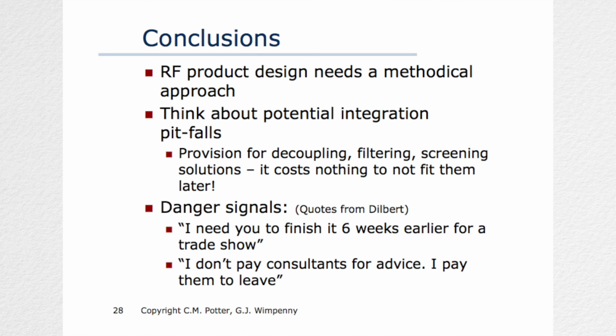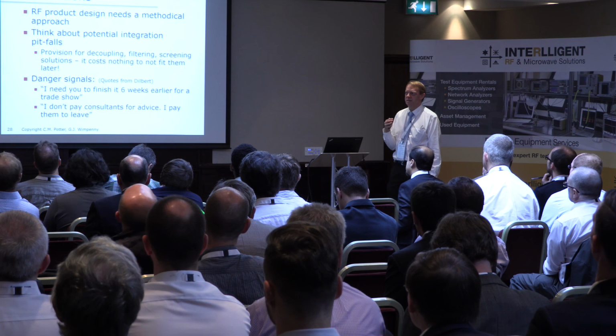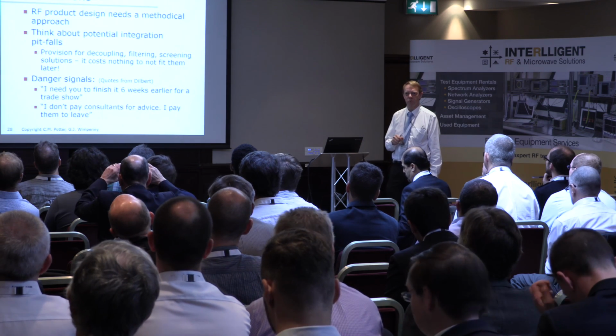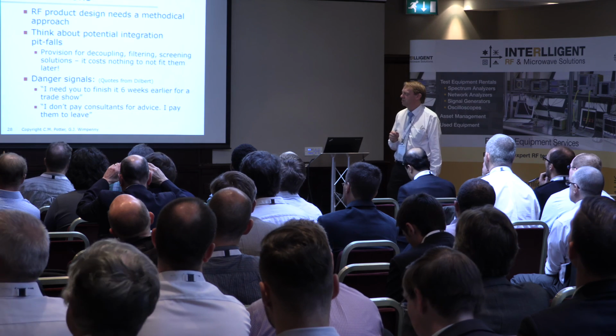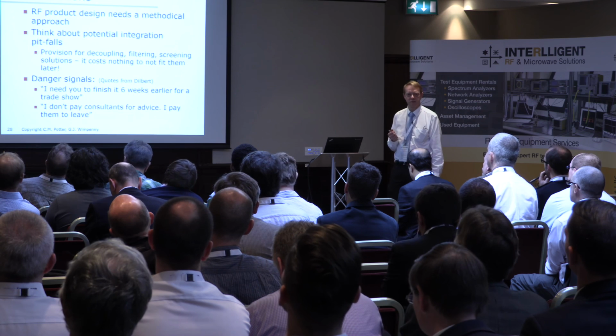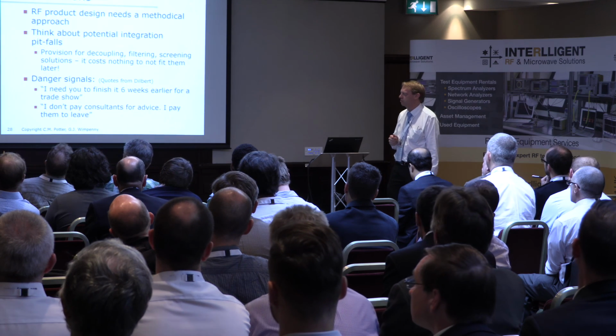So at that point, final slide, you may have guessed that I advocate a methodical approach to this and not doing a sort of fast and loose hacking of circuit boards, no matter how fun it is to play with soldering irons and little components. There's a stopping and thinking about it stage that's required first before we actually get into doing the actual circuit design. And the thought process about what could possibly go wrong needs to be thought through all the way from beginning to end. Maybe planning to decoupling, screening, ground planes, all that kind of thing, right from the beginning all the way through the product's development.